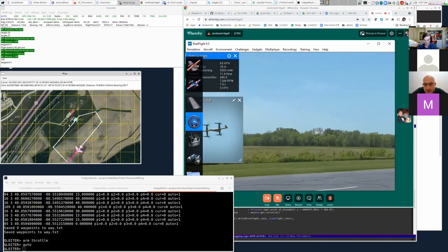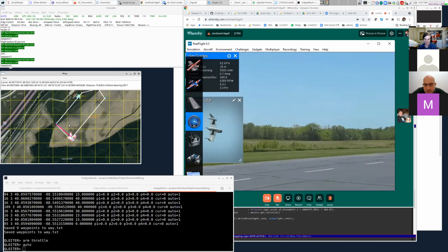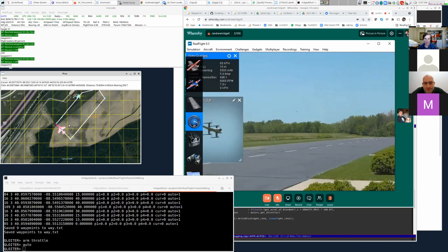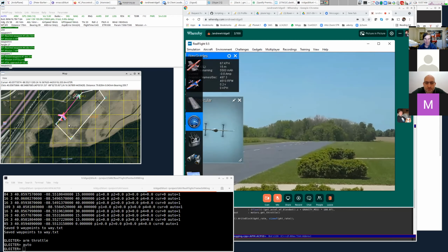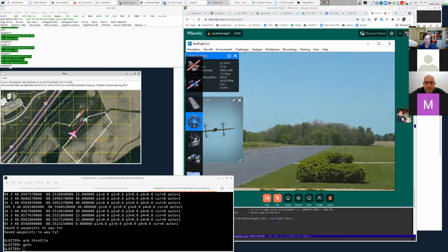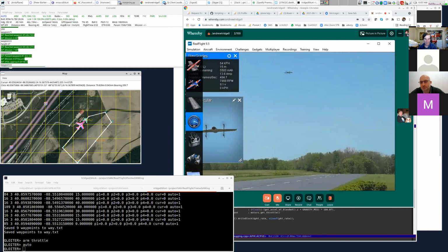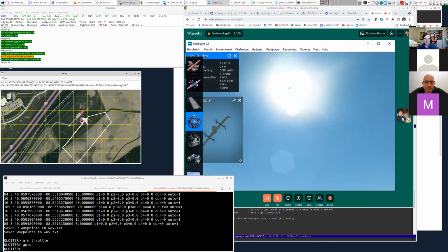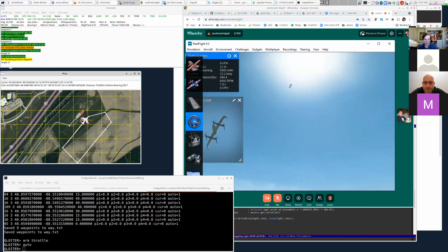It does have downsides. It's not lockstep scheduled. It's not CFD, so it's not perfect physics, but it's very good for this type of thing where you can construct an emulation of a vehicle very quickly, and you can edit the vehicle with the exact motors and propellers and batteries and masses of objects, all the parts, just like the real vehicle. And you can quickly gain some confidence that the vehicle's got a chance of flying reasonably. You can see that it actually did gain a fair bit of height there, about 15 meters in that back transition. And now it's coming down to land.